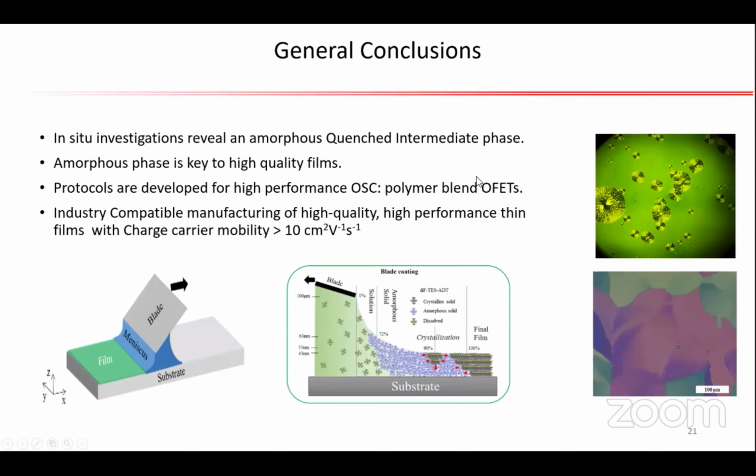We developed protocols eventually to basically coat thin films based on small molecule organic semiconductors at industry compatible coating speeds of 100 millimeters per second with charge carrier mobility of more than 10 centimeters square per volt second.